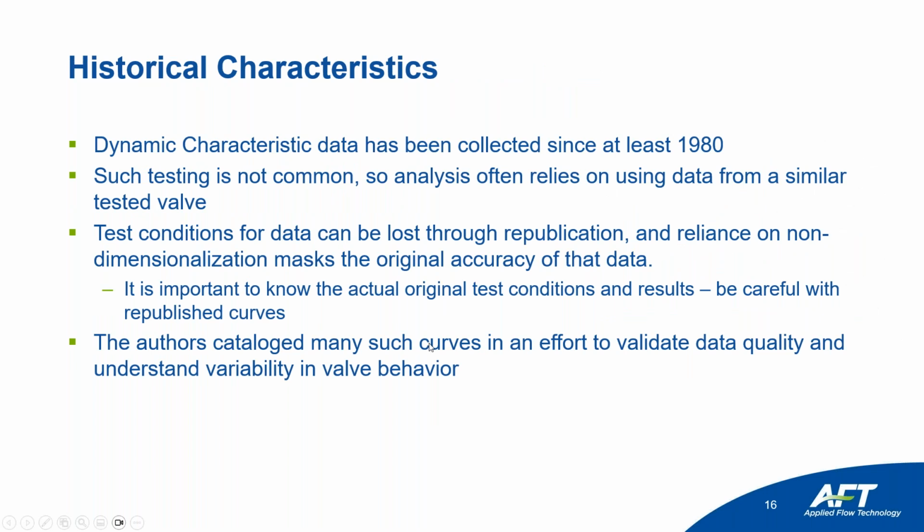So this data has been collected since at least 1980. It's not common for manufacturers to do this kind of test, so it's usually done in a specialized flow lab. And the actual test conditions, the dimensional data, things like that can be lost over time through republication. And it's important to know what the actual original test conditions are, especially if it's a non-dimensional valve. There might be a dramatic difference between, you know, what was tested in the lab was a 3-inch valve and you're trying to scale that up to a 20-inch valve. That may be dramatically different.